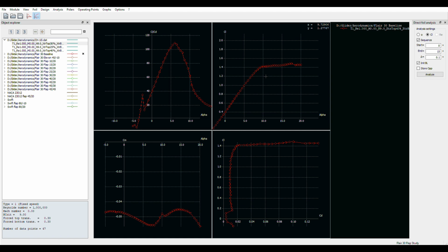This airfoil is not performing efficiently. It crosses the zero lift line somewhere over here at a negative angle of attack, which for a flying wing is not necessarily a good thing. Generally, that means you need more washout to counteract that nose down pitching moment. But we know that the Flair had only 5 degrees of washout in the wing. That was probably just barely enough to fly.